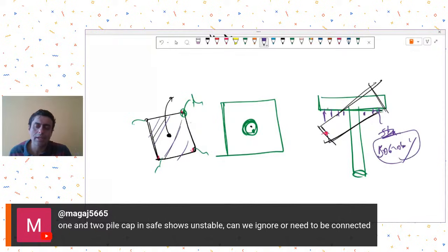Corresponding to that, you may provide some spring constant. Just tie these four points for translation restraints also, and see that there is no area load getting applied on this. Otherwise, you will get problems.